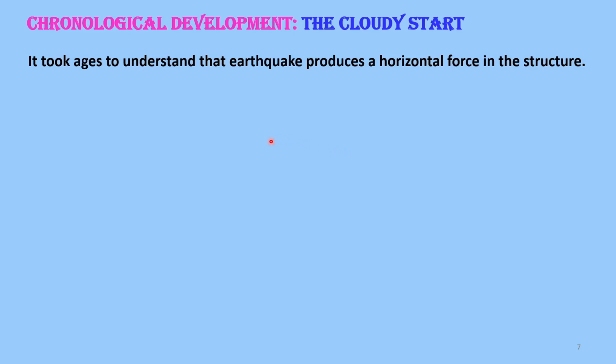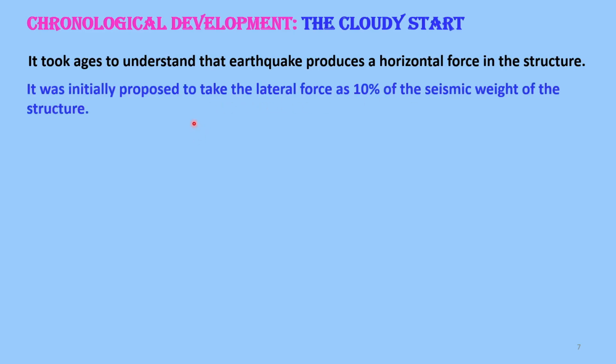So after applying intuition, they understood that it is producing horizontal force which is shaking the structure and causing damage to the structure. So how much force it is producing, so that I can design for that force, that question arose. Initially it was suggested that 10% of the seismic weight of the structure can be taken as the lateral load for design purpose.